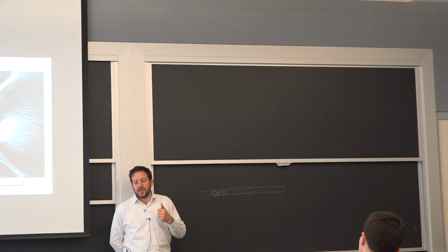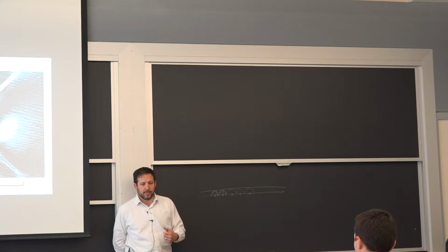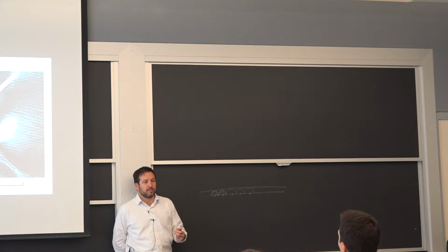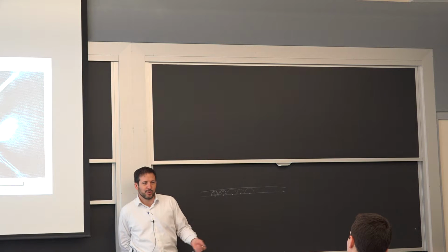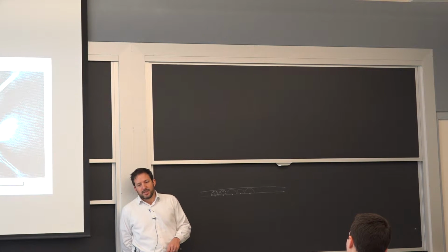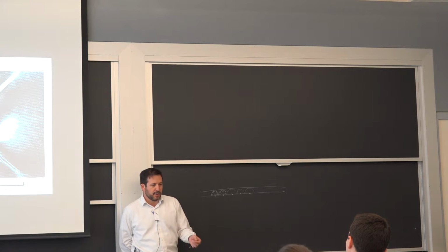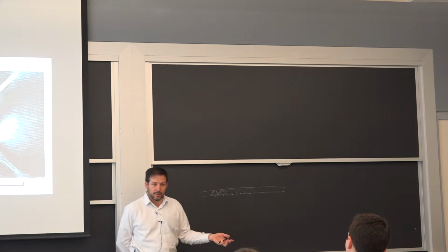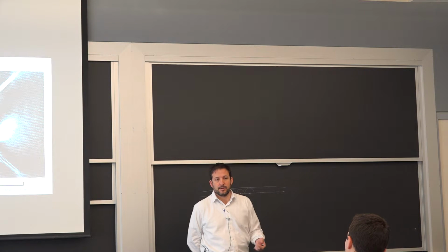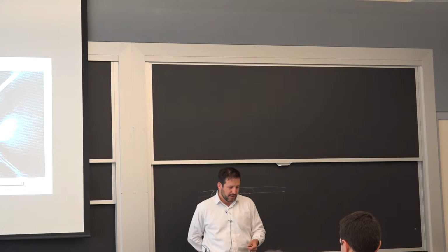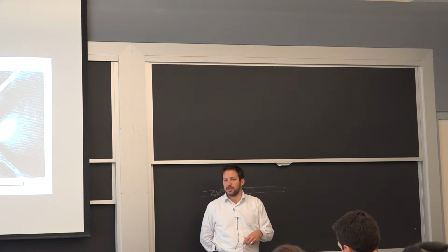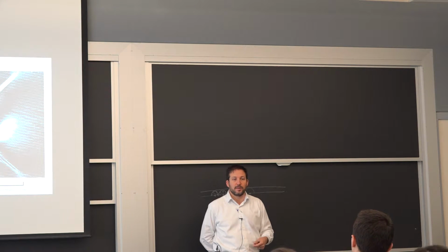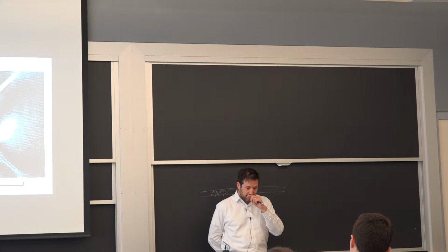Perhaps, and that's something, unfortunately, we don't have a huge amount of time to talk about, but just because you have plastic doesn't mean you can rule out potential problems with the environment. A lot of plastics will degrade from UV light, and I think from common use you are probably familiar with that. Just time itself and the water. If you have plastic pipes that carry potable water, there's a lot of oxygen in that water that will over time degrade the resin, especially polyethylene. It's a little bit counterintuitive, but some of the very long-term effects are within the structure. You can start breaking chains. There's a lot of things that can start going wrong within the polymer. It's not that you're losing section, but you definitely are losing capacity over time.